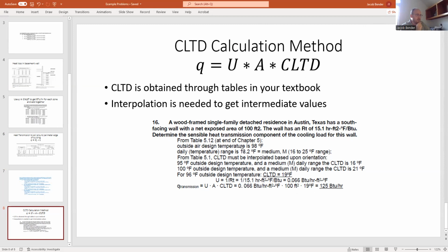I will note as well, for separate cooling calculation problems, there are some that utilize Q in a not so positive way, where you're using Q as a value for the amount of airflow that's run through space. In the same problem, they use lowercase q for your heat loss. It doesn't go over a whole lot, but the numbers in front of that, it's 1.1 times your airflow Q times your temperature difference.